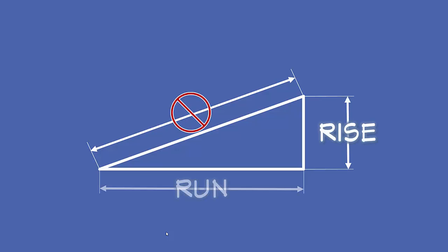And another reminder, you should not dimension the slope of an angle. Just don't worry about it. We're more concerned about the rise and the run and the points of those angles than the actual slope of the angle or the length of that slope.